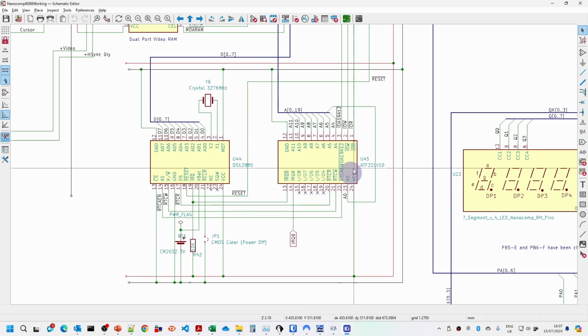All we've really got here is we're taking the address bus and the data bus down here. So this is a programmable logic device which we're taking in the IO read, IO write, and there's a signal here which comes from the other decoder that just tells us when all of the A12 to A19 address lines are 0, so it makes it easiest for us to decode the IO addresses.